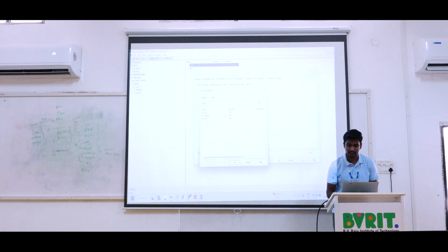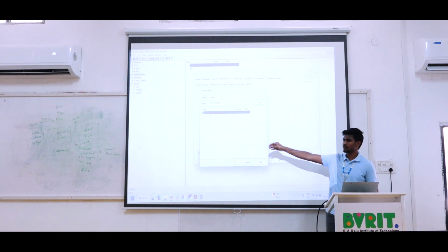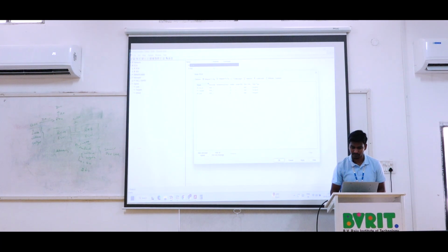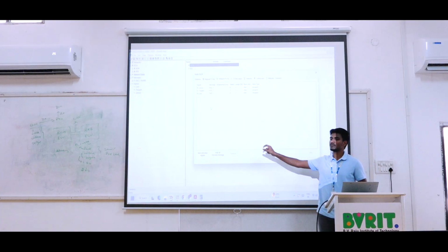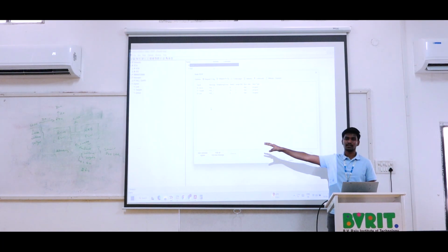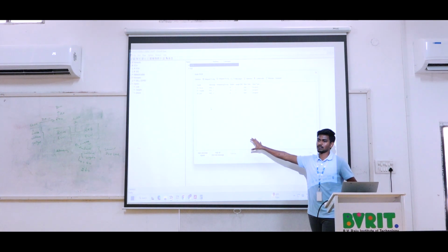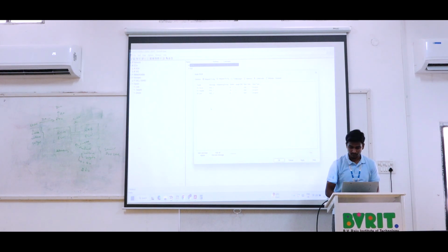For example, if I add individual signals, I need to select one and then another like that. If you add from one message, I can take the entire message. This message consists of only 3 signals, so they are directly added. Just now I give the message, click OK, and automatically 3 signals are mapped here. We do not need to select individual signals. But in some messages we don't want all the signals, so at that time we select the particular signals. Okay, sir. Now give apply and then OK.